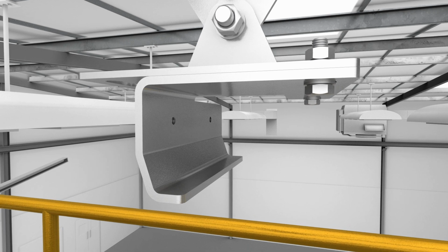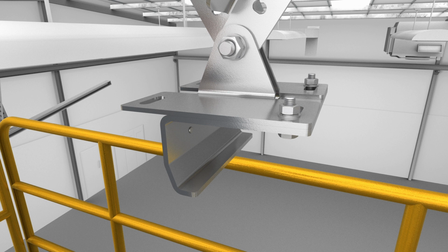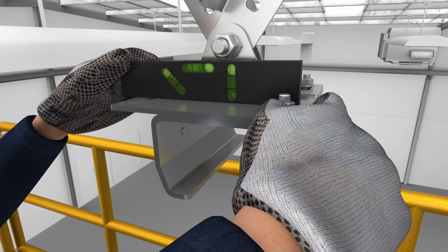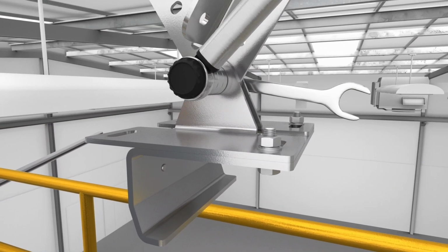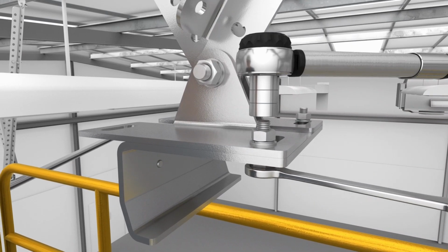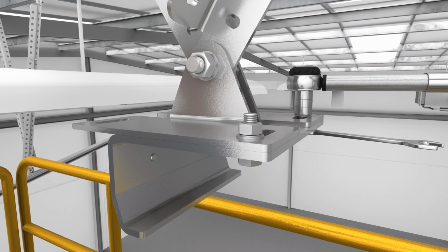The half clamshell bracket should be orientated parallel with the direction of the rigid rail, ensuring the half clamshell opening is facing towards you in preparation to install the rigid rail. Prior to tightening the central M16 bolt assembly, using a spirit level, check the assembly is level. Tighten all bolt assemblies to the torque value shown in the torque settings table.